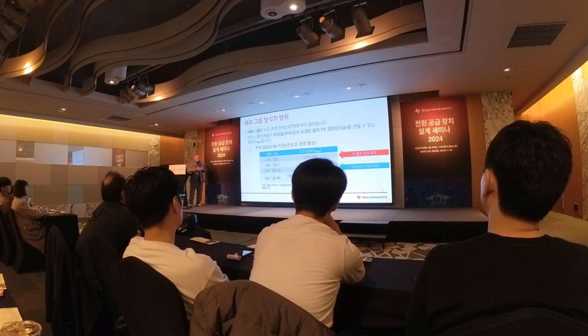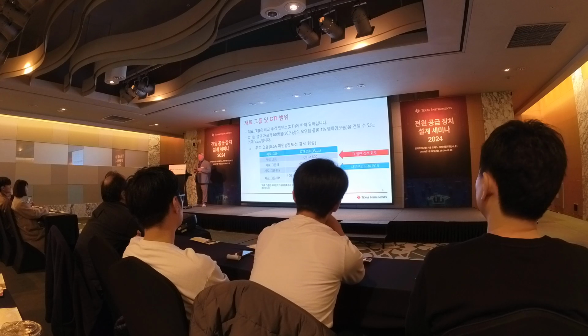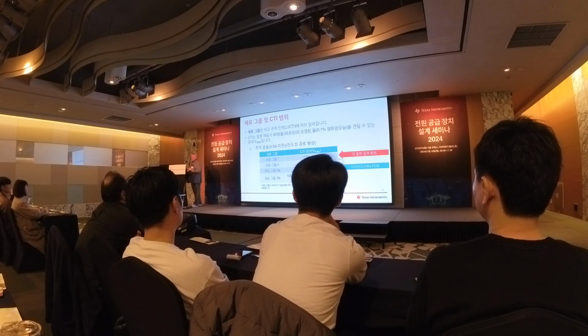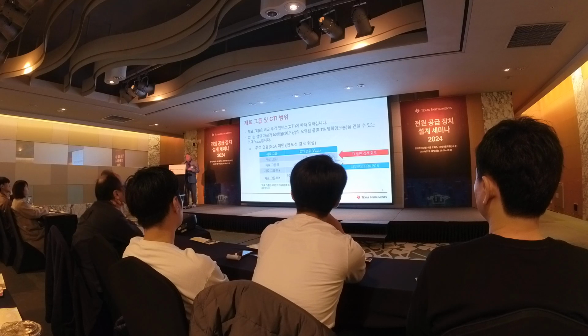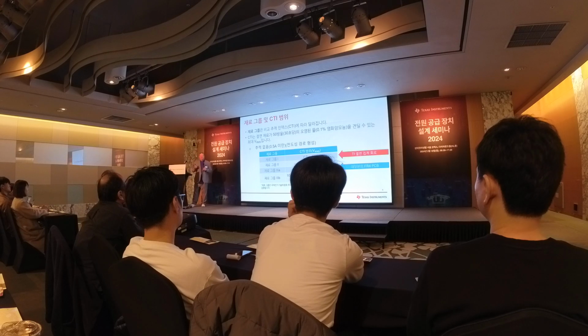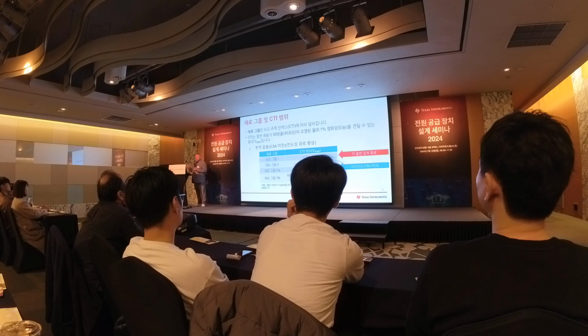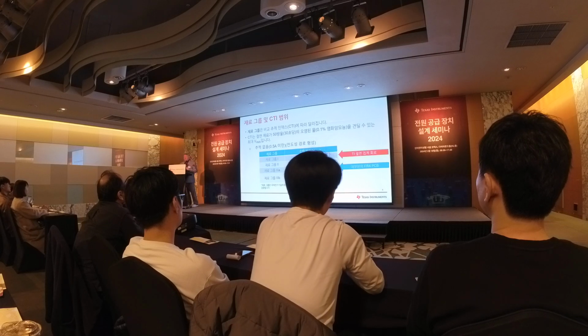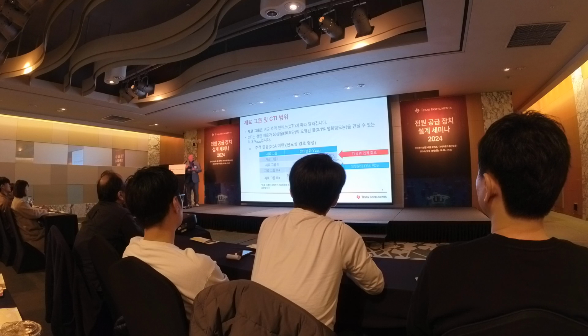So this is going to lead me to a number of different material groups, and we've listed those here in a table. So material group 1 is any type of material which can withstand higher than 600 volts RMS. So typically you will see material group 1 are packages that are on semiconductors. For example, an isolated gate driver from TI. The package would be made from material group 1.